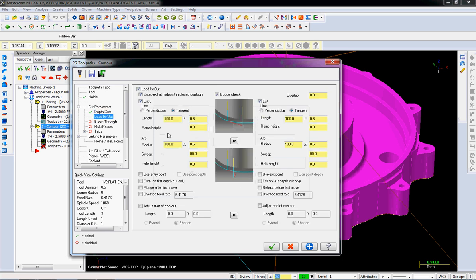Lead in, lead out. Use this all the time. This makes the start and end point of your contours, it keeps it from having a bump as you bore down, and the imperfection of some machining and deflections and all that sort of stuff will leave a little bump there. The lead in, lead out will, just like in this picture, come on an arc and then go tangent to the contour, and it's a good way to do it.